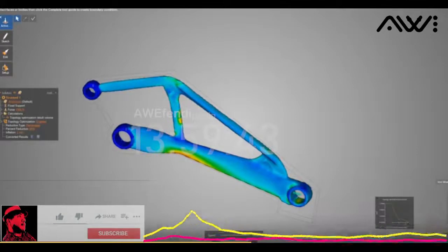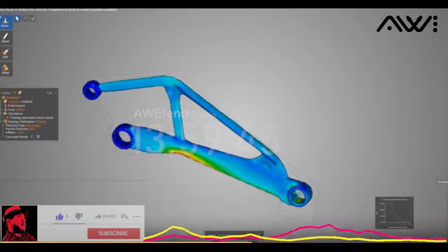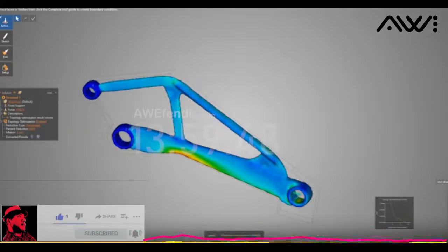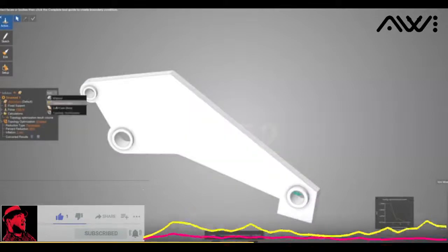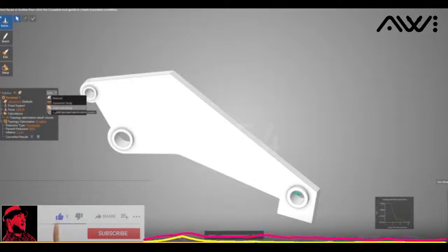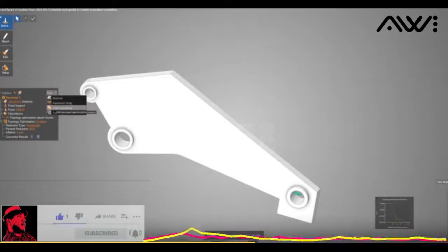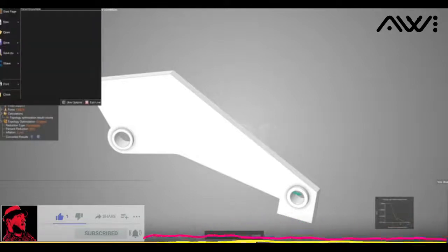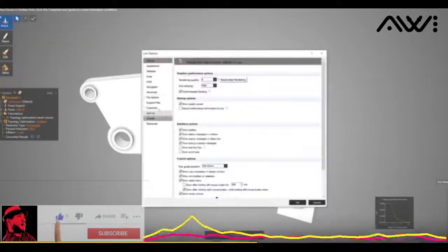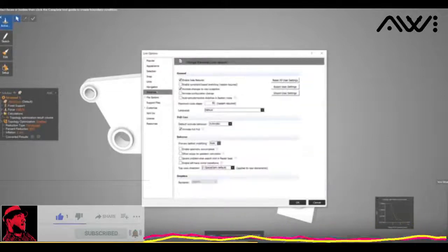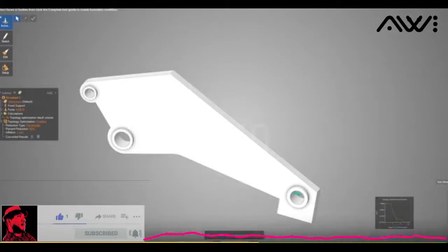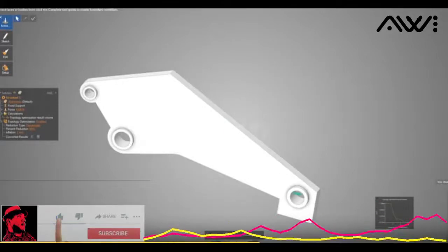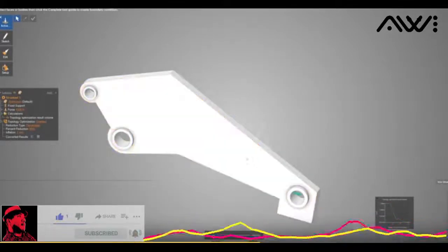But the forces are not going to be just at that one location. So let's talk about adding additional forces, right? That's what it's about when you start diving in here. So what we have that's still in beta today, that will be coming out of beta in our next release, is our load case. If you ever want to get to these options, under File, Live Options, you're going to see under our advanced area, just turn on Enable Beta Features. This is how you can access all of our cool beta functionality that's coming out, and then always give us feedback in that round too.